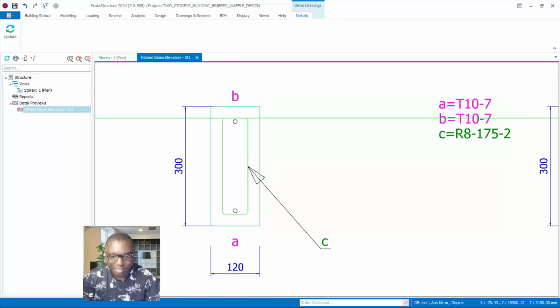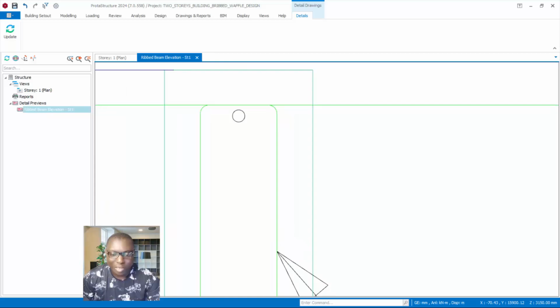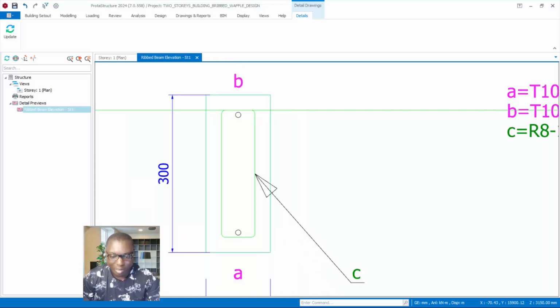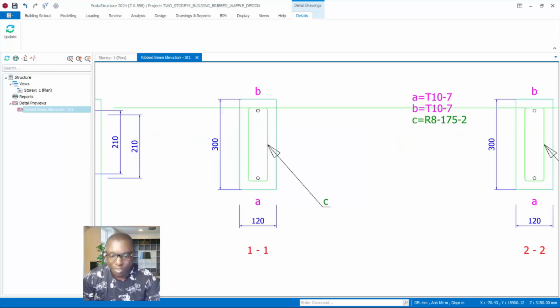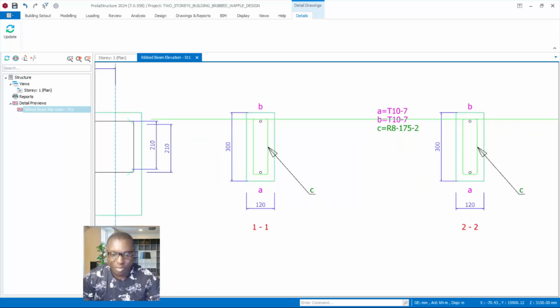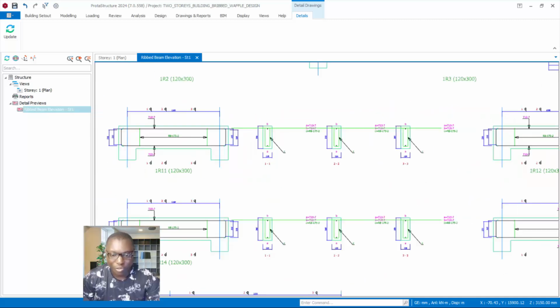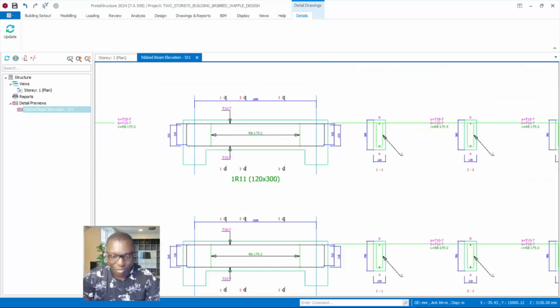We are having one reinforcement top, and then one reinforcement bottom, that is in the tension and compression zone successfully. And then we have another tab, which is the reinforcement for the concrete topping. You can now see how the reinforcement is being arranged. But all of this, you can make changes if you wish. I will show you how you can make changes to this successfully.